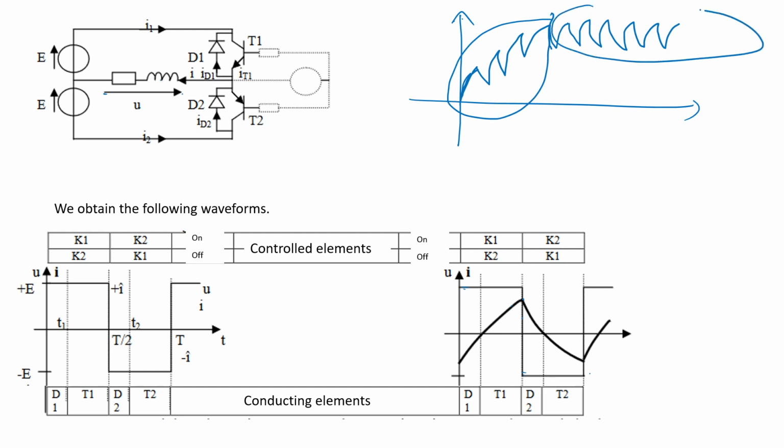But during this part, it is periodic steady state. Right? But if you look in detail at this part and this part, actually it's just the transient of the response for the constant voltage. Because it's constant for a period, and then it falls to a different constant like this. Yeah, if you understand these two concepts very well, you can easily draw the response.